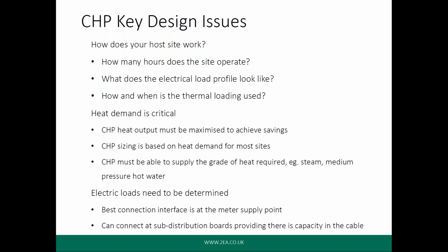So let's for a moment think about how to pick the right size combined heat and power unit for your building. These first 3 points can seem like common sense, but in my time I've seen plenty of examples where these points have not been properly considered and have led to dissatisfied customers with an investment that is not providing the promised returns. I'll come back to these 3 points in the next slide, but I cannot emphasize enough how important it is that as much of the heat as possible is utilized. As we saw earlier, it is the inclusion of the co-generated heat that gives us the large combined efficiency of the combined heat and power unit.